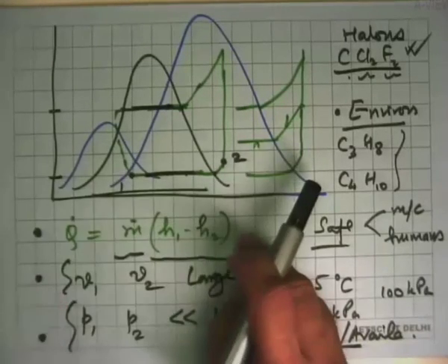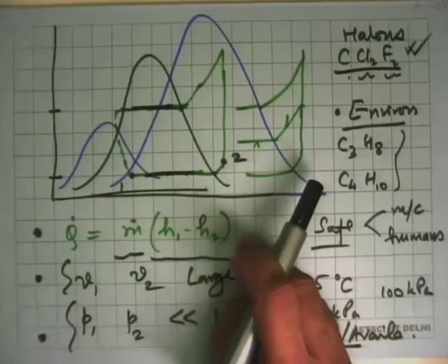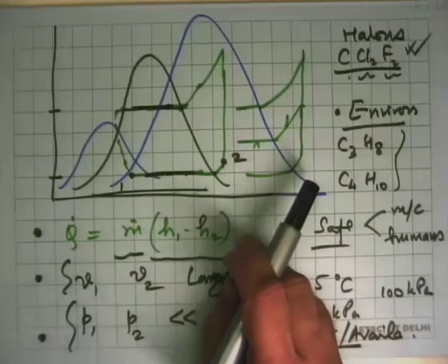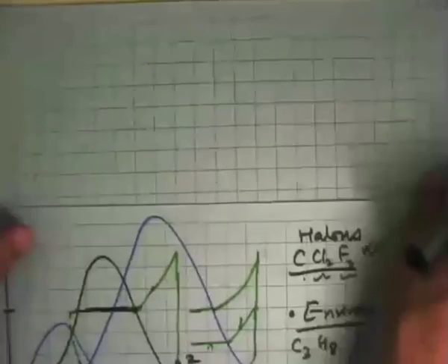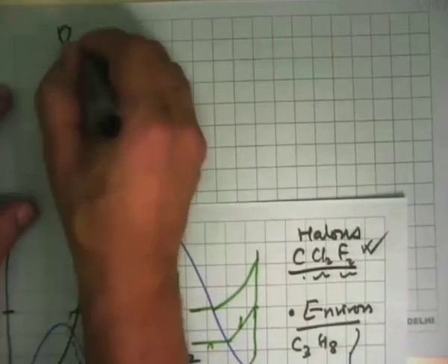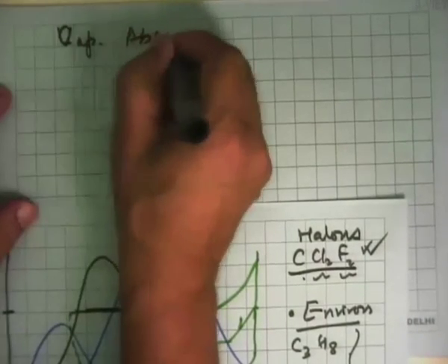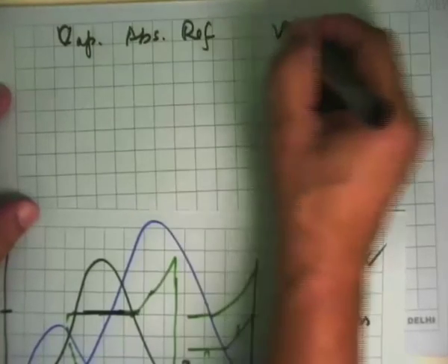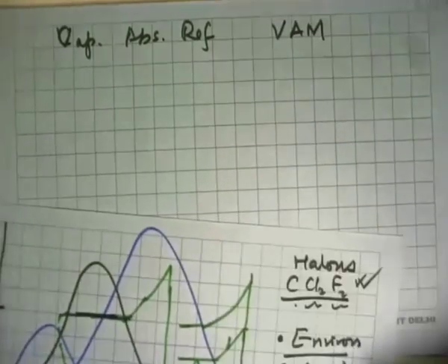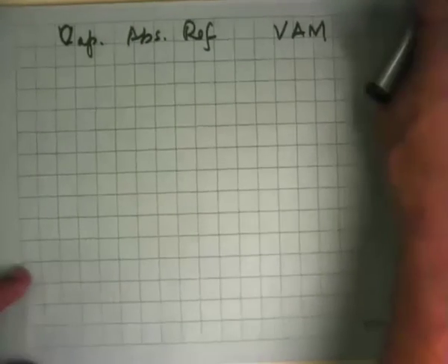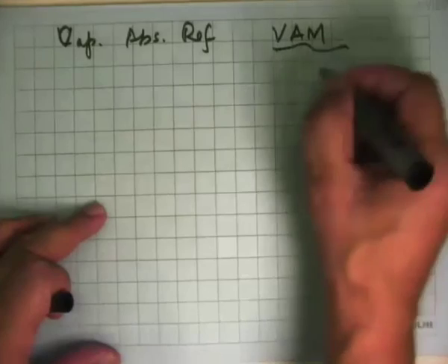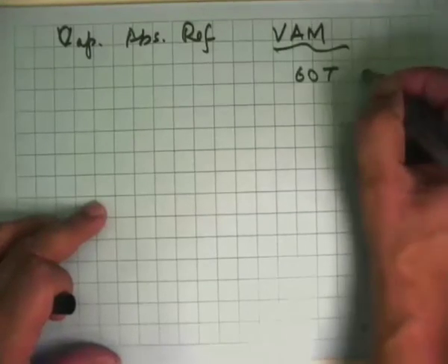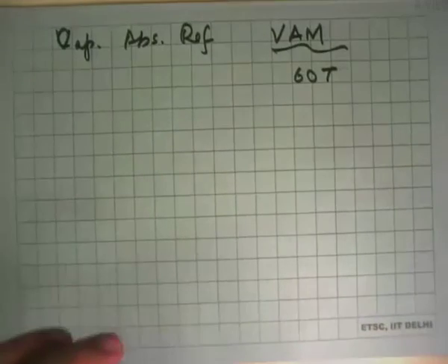Okay. If the thermodynamics doesn't make sense, then we are in trouble. Might as well forget that material and go to something else. So before I leave this, let me tell you that water is used as a working substance in a refrigeration machine called a vapor absorption refrigeration system, or vapor absorption machine, VAM. We cannot make very small window AC type of things with VAM, but large things like 60 tons of refrigeration or bigger, 300 type, they are very much there.